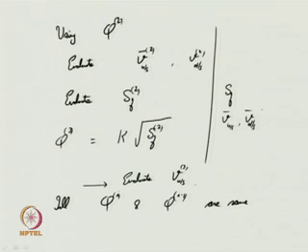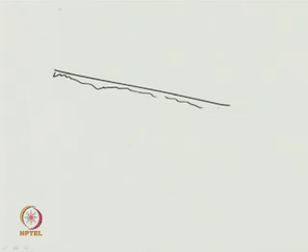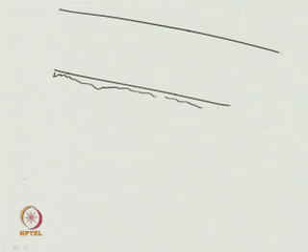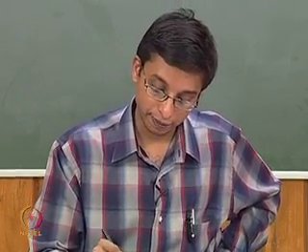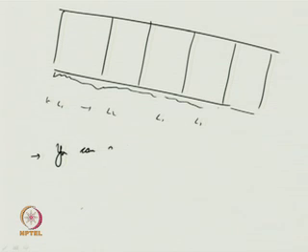So, this is how you compute the flood discharge using uniform flow approximations for natural streams. As I mentioned earlier, you are dealing with the entire channel reach. If there are many such reaches of different lengths, say L1, L2, L3, L4, L5, up to n, then for the entire natural stream you can average the discharges.